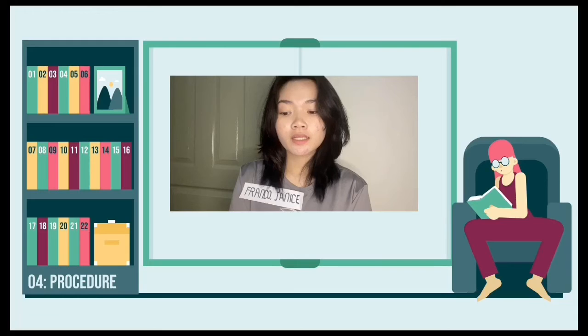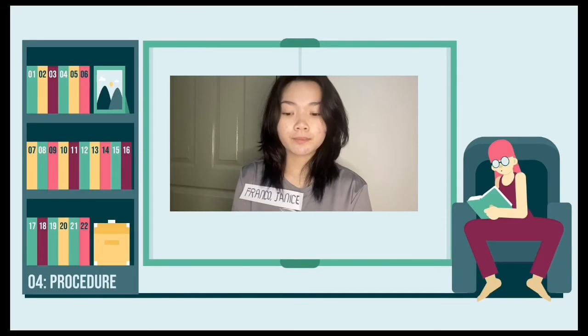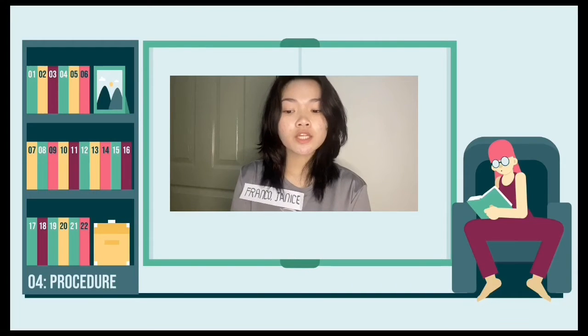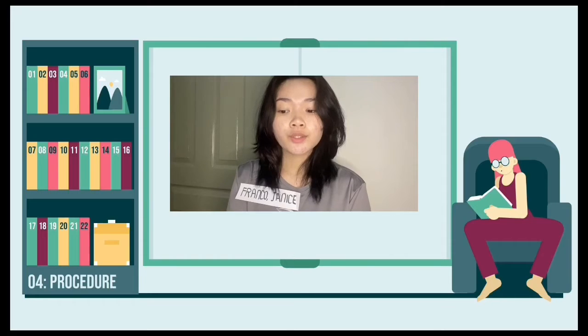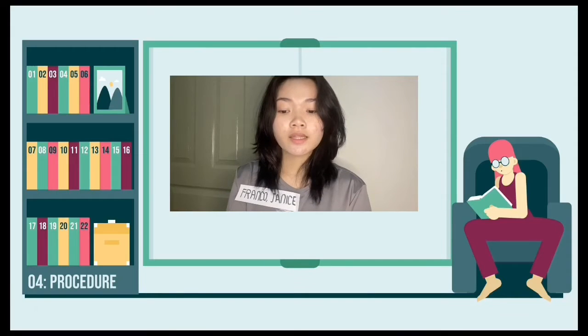Fifth, click and drag the ammeter and place it on top between the battery and resistor to determine the experimental current. Sixth, connect the ammeter, battery, switch, and resistor using wire. Seventh, click and drag the voltmeter and connect the tube probe in resistor to determine the experimental voltage. Eighth, click the resistor and set the resistance in an increasing manner, then click the current electrons and conventional, then observe what will happen.